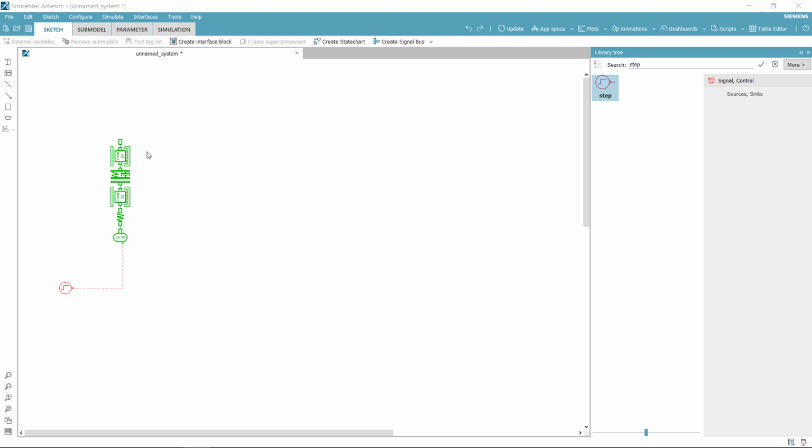Once your components are placed, you can select multiple components by holding down the Shift and clicking to select or deselect each component. Draw a box to select or deselect groups of components by holding the left mouse button and moving the mouse to define a rectangle. Use Ctrl A to select all components in a sketch.